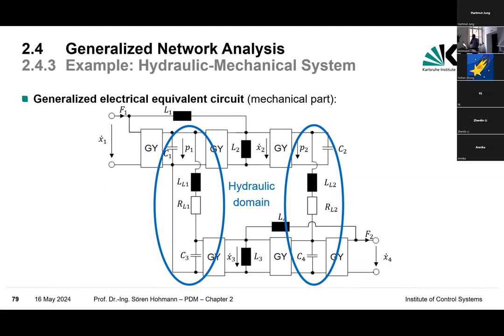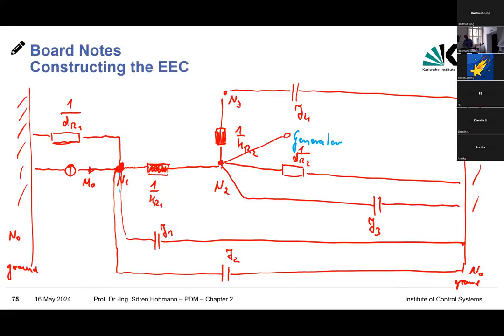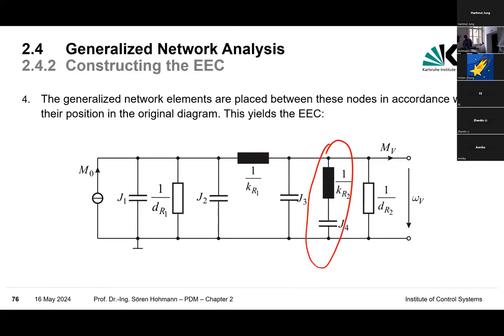What is interesting in addition, perhaps back to our example here, I wanted to mention, well, here we talked about this oscillator, which is included here to damp down the various frequencies or eigenfrequencies which are given for the shaft and which are safety critical because the shaft can break. Due to this fact, we introduced this red encircled element on the mechanical side.